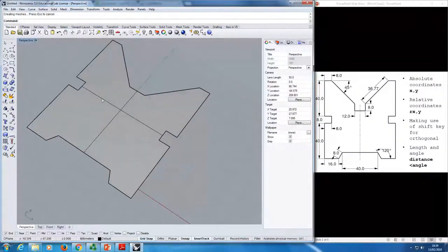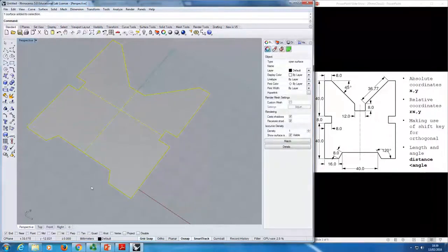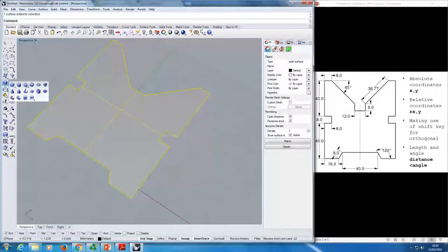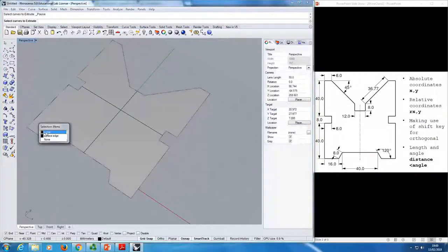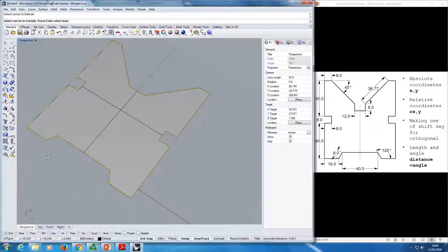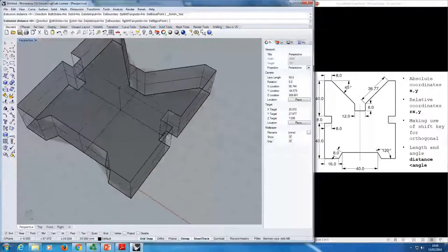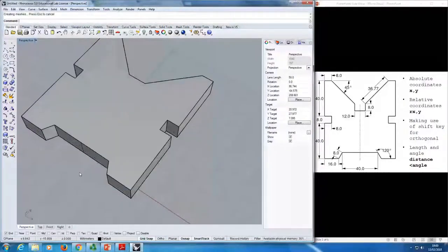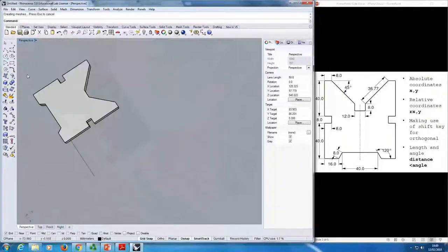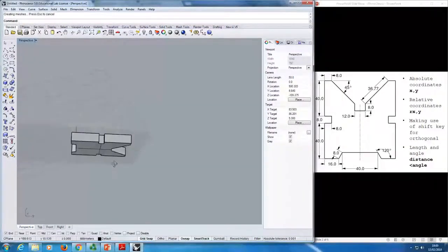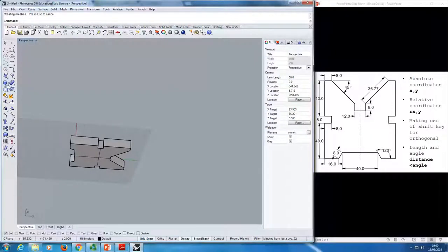And now if we wanted to create a solid, we can extrude this. So this one is the solid menu. So there's two ways to extrude. You can extrude from planar curve or extrude surface. So we'll start with planar curve and we'll take curve. And we can extrude, so if we type, for example, whatever. If you extrude one side or the other, then you'll get something like this. The other one I was talking about was extrude surface.